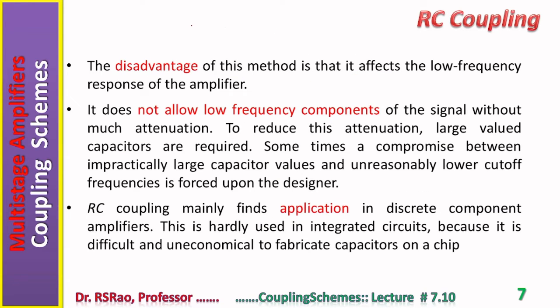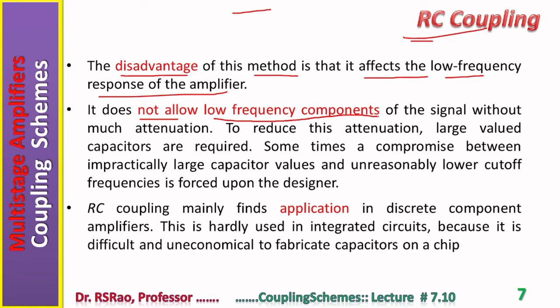It is associated with certain disadvantages also. What are they? The disadvantage of this method is that it affects the low frequency response of the amplifier. It does not allow low frequency components. Notice RC coupling prevents DC totally, completely from entering into the next stage, only DC.